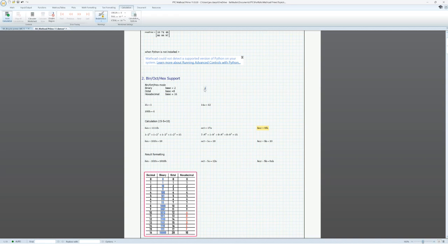For example, when I have a binary number 101, so I added the table on purpose, that's the decimal number 5. When I say 101, I have to type it correctly, and I type B, Mathcad thinks it's a multiplication. And since B is not defined, I will get an error. In order to cope with this, I need to activate the binary octal hexadecimal mode. And starting from now, when I do the same, 101B, it will paste the B, so to speak, to the value. And as a result, now it is able to interpret my input.